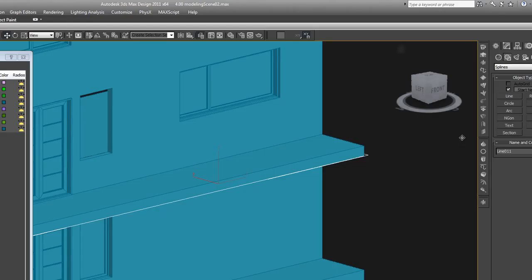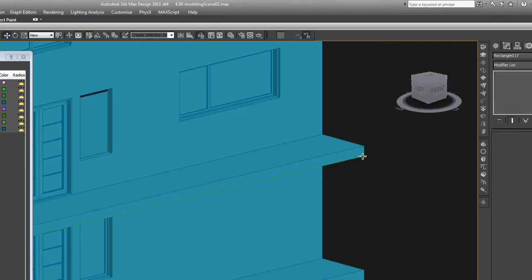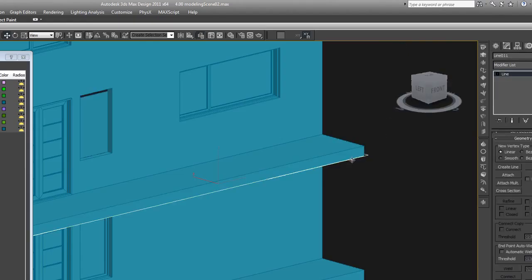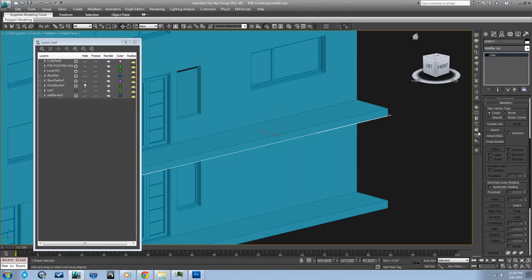And what I will do, let's see, an easy way to do it, let's check to see what this is extruded at. That is -10 inches. These railings on the second floor deck like this would be 42 inches above the floor. So that'd be 42 plus the 10 if it's going to be face mounted there. So that would put it at 52 inches.